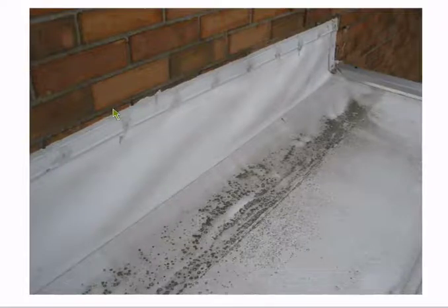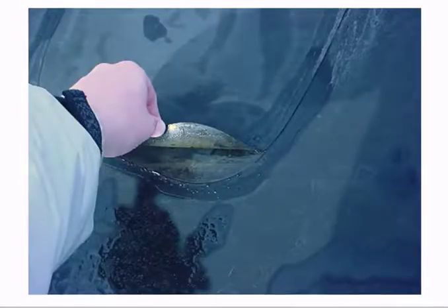So we'll address later in the presentation some really good long-term solutions to this very common detail. But again, we don't want to rely on sealant. So if we come back and run into the situation that's leaking, caulking might not be the best solution. We might want to redesign this detail. It's more of a strategic repair approach to make sure it's a real long-term solution.